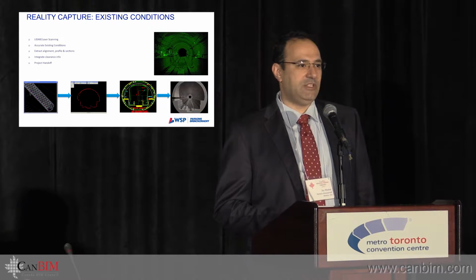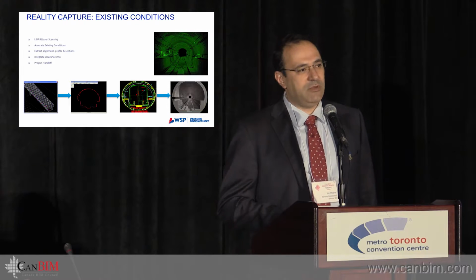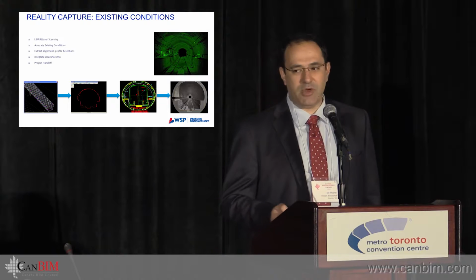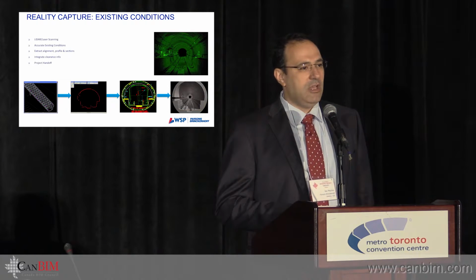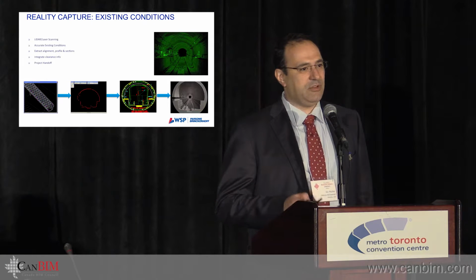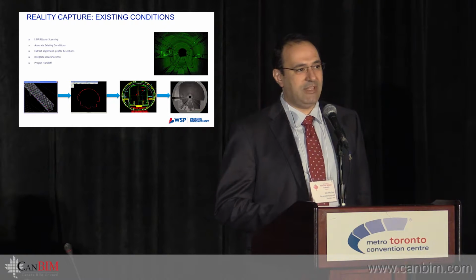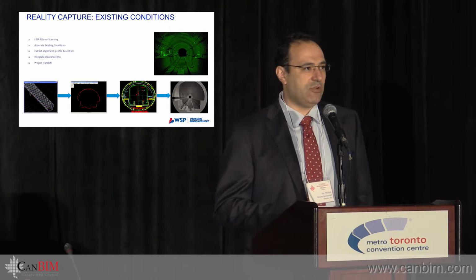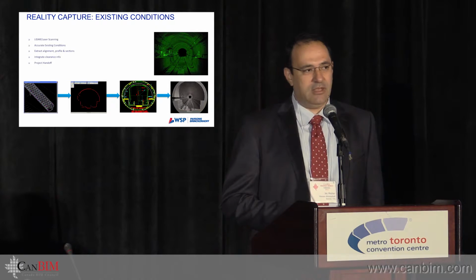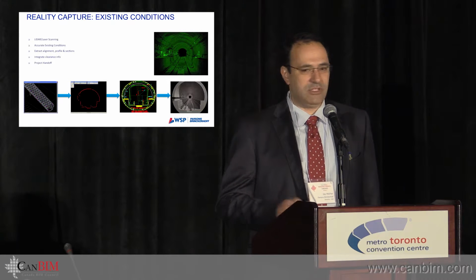First is validation of proposed design with existing conditions on projects like a tunnel. It's really critical to have those spaces clear, measured and surveyed accurately so you can overlay it with a proposed design, make sure there are no conflicts, and submit it to the contractor and eventually to the owner.